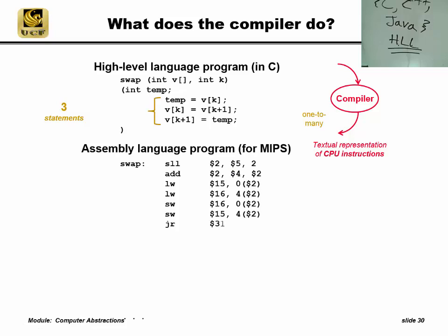So let's take a look. Here is assembly language for MIPS code. We said load word was a MIPS type of read, and store word, SW. These are mnemonics. They're helping us remember this by a sequence of characters. So store word is actually writing to memory, and here are operands. And this is how assembly language is laid out. You'll see in the lab you have an instruction followed by some operands. This could be an output operand for MIPS and a set of input operands, and we'll discuss this. But the machine still cannot execute this sequence of assembly language. This is for the human to read. We have to convert this to a sequence of bits.